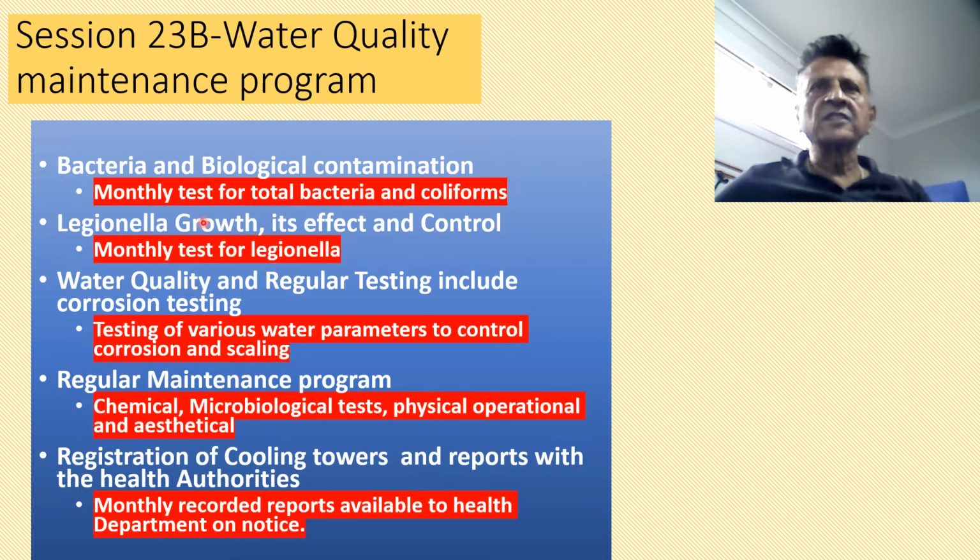So it is important that we check for Legionella in every tower to ensure Legionella is not present. But rest assured that if you fail to have a very highly reduced biological load in the water, the chances of Legionella growing will be very high.